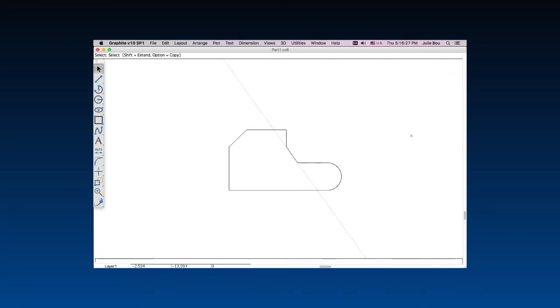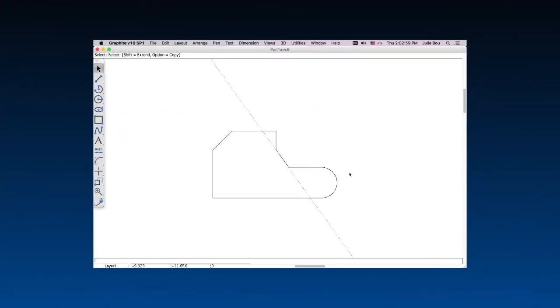So let's use the stroke commands to set up the view for the exercise in the next video. First, let's create a construction line from the endpoint of our horizontal line in the middle of our figure. Holding down the designated stroke key, I'll draw the line. Now use the drafting assistant to find the midpoint of the upper horizontal line. Again, I'm holding down the designated stroke key and drawing a vertical line straight down from the midpoint.